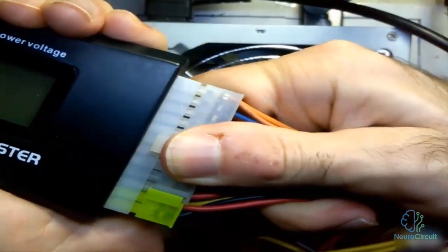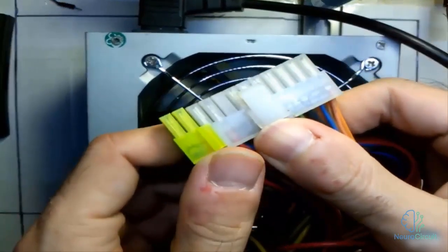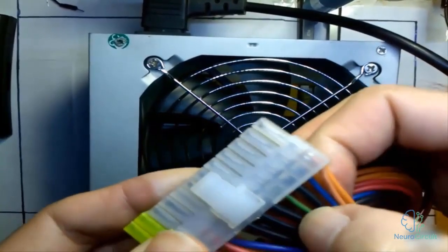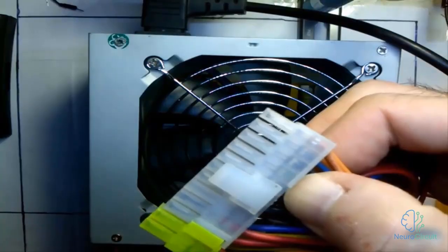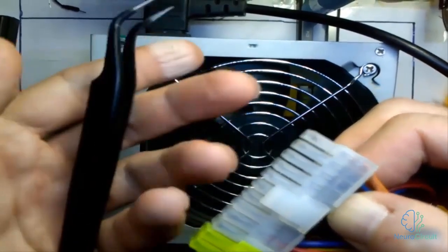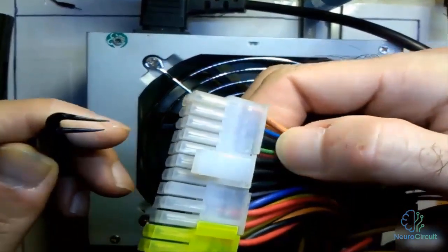We'll test the same power supply using a multimeter as well to see what its output voltage is like. Since I've disconnected the power tester, I need to come here. We can see the green and black wires here, and using a pair of tweezers, I need to connect them together so the power supply turns on and I can test it. Here I'm bringing a pair of tweezers. Try to use the tweezers you see here, which are black handled and commonly known as Z tweezers.